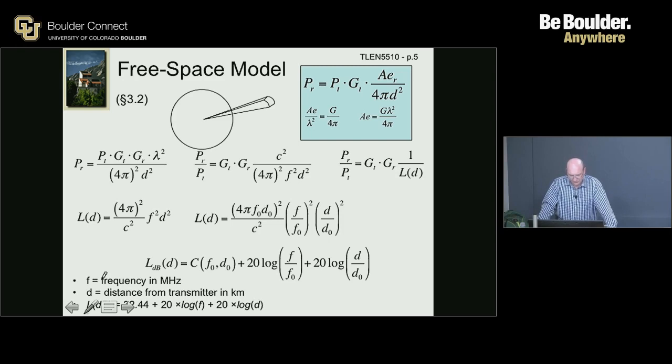Well, you receive the transmitted power times the gain of the antenna that transmits that power in that direction times that fraction of the power that intercepts that area. So that's the ratio of that surface divided by the surface of the entire sphere, right? Because the power is conserved, but the one you can only receive is a certain portion, the one that your antenna sees. So it's the ratio A sub R of the receive side divided by 4 pi d squared, the whole surface of the sphere at distance d.